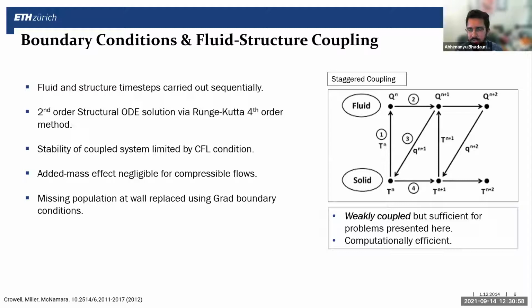The stability of such a system, in our case, is again limited by the CFL conditions. The RK4 solver, the ODE solver, is quite stable, and we're only limited by the fluid time step. Another problem that usually arises due to the nature of this first order coupling, which is the partitioned staggered coupling, is this added mass effect.